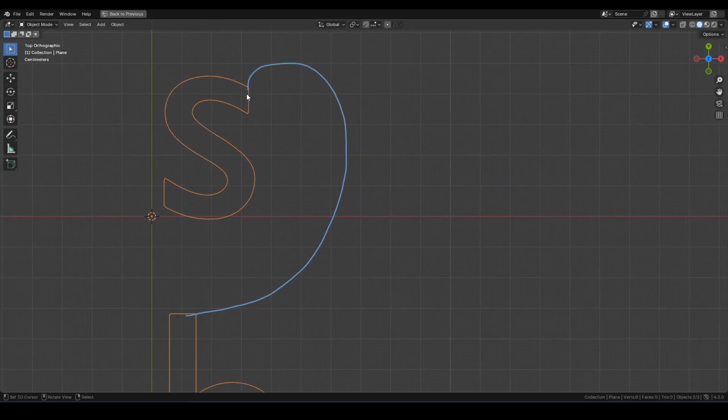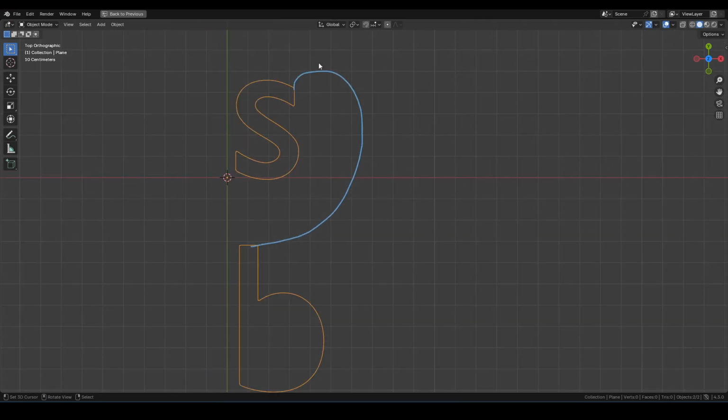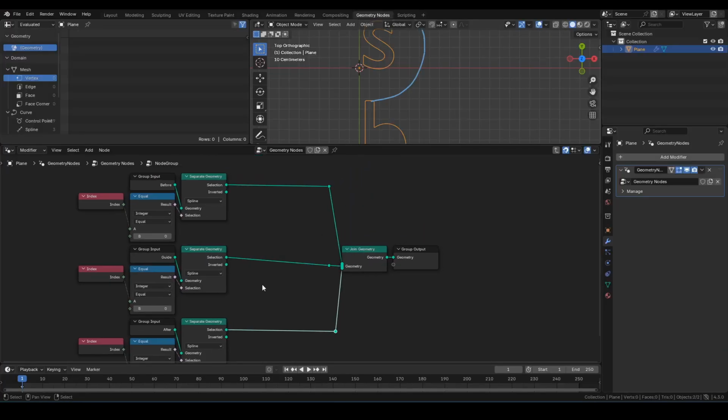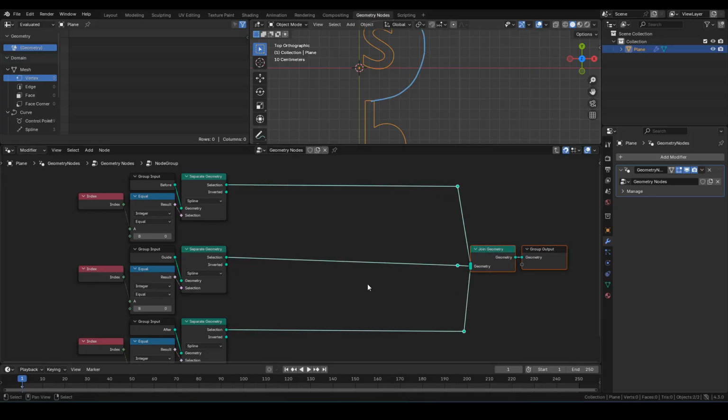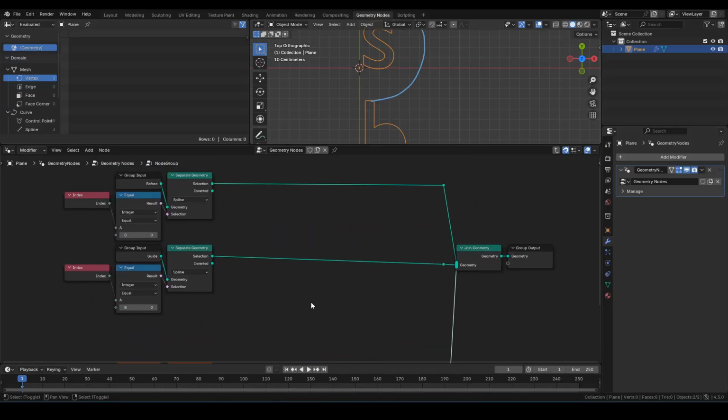The way we're going to do this is we'll grab the end point of S and we'll connect the guide spline, well, start of the guide spline to end point of S, then end point of the guide spline to the start point of B. Okay, and we'll make it curve around. Right, so this middle portion is going to be the guide spline. So let's create some space. I'm gonna actually create some space here as well.